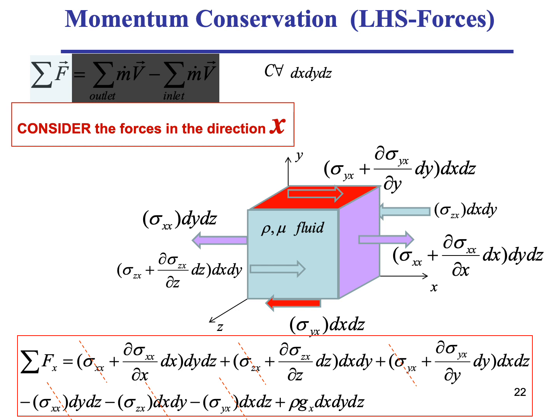And now we want to do the same thing for the forces. Let's consider the forces in the x direction. So anything where the second subscript has x, this is the second subscript, we'll sum all those up. So you'll see I have sigma xx on this face, on the x face. On the top face, on the y face, I have sigma yx, so that has the x direction. We're talking about the x direction.